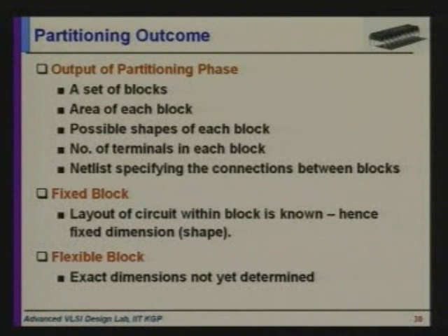One industry standard that was used till recently was Fiduccia-Mattheyses. Probably it's now also used. It allows hypergraphs. So I don't have to do an exchange, but I can just move a component from this partition to that partition. It also allows unbalanced partitions, right? That is also required. Now I need not have a partition where all partitions contain an equal number of vertices, right?